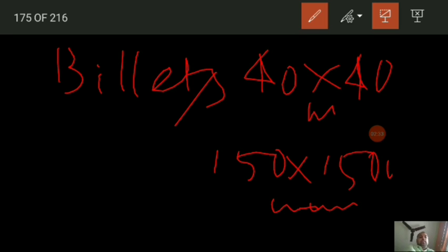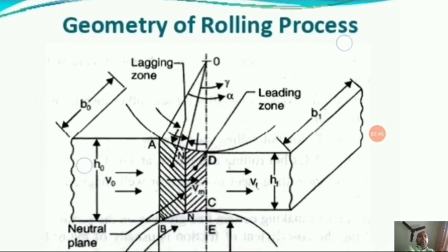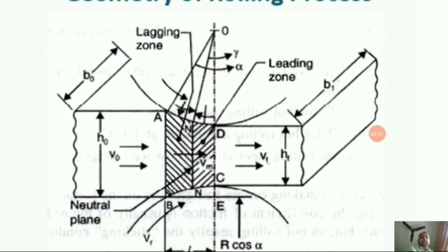Now the ingot obtained by casting would normally have defects such as shrinkage cavities, blowholes, and slag inclusions. When the ingot is rolled, the shrinkage cavity, called the pipe, is towards the end, which is then cropped after a few initial passes to reduce the defects in the finished product.